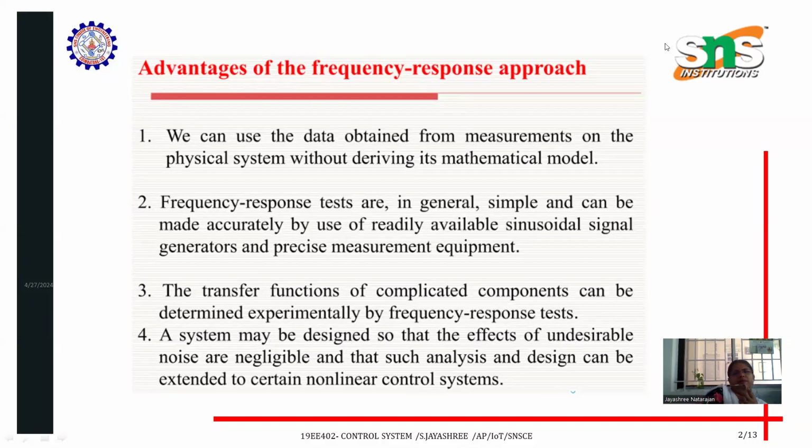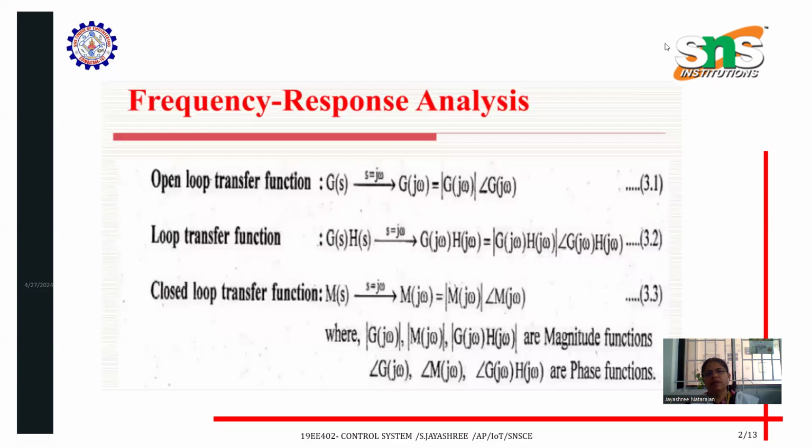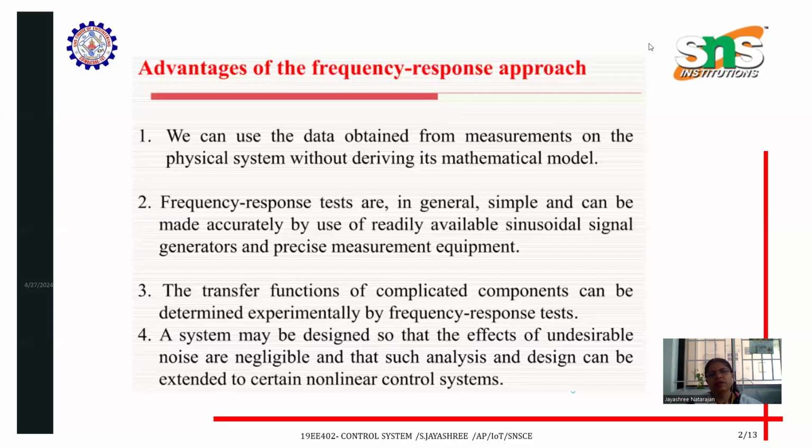Okay, we continue with the previous topic about frequency response analysis. In the previous lectures, we discussed what the transfer function is, and open loop and closed loop transfer functions. Now, what is the advantage of the frequency response approach? We can use the data obtained from measurements of the physical system without deriving its mathematical model. By measuring the data of physical systems, we can analyze the response of the system for various inputs.